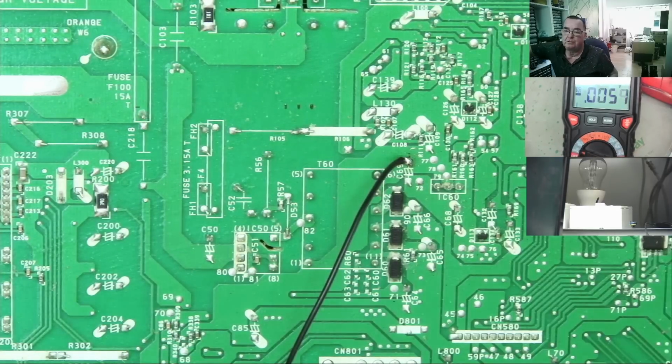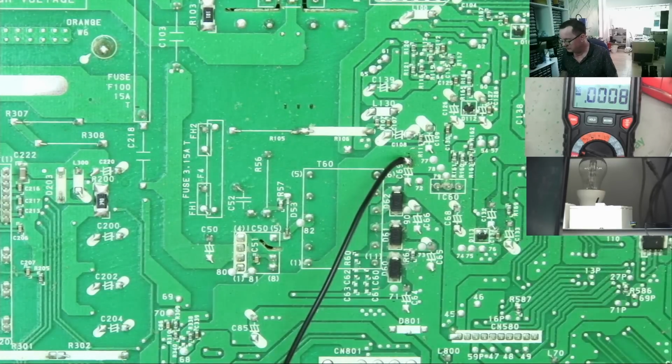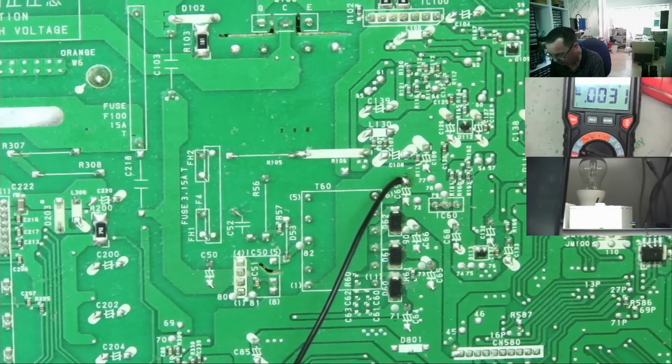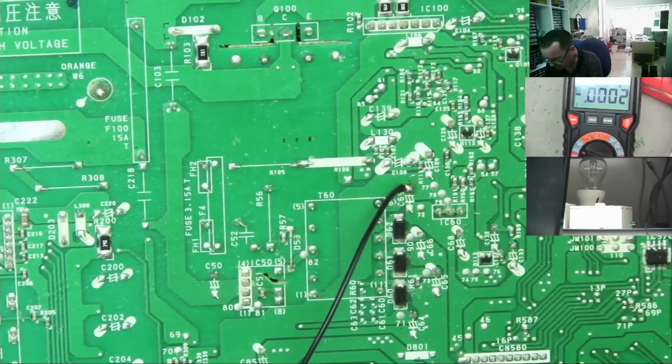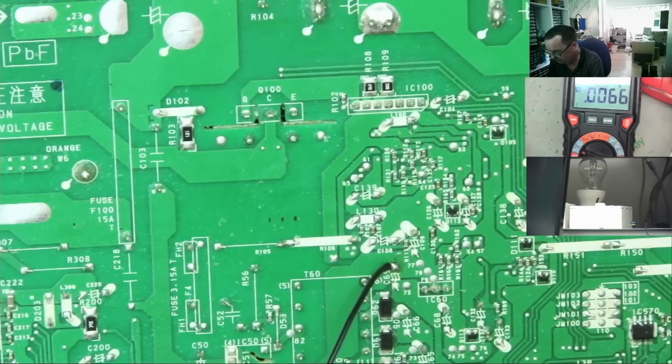Okay, volts range, you can see the current limiting bulb up there, so we're going to switch this on now, and hopefully the bulb won't do anything. It came on bright, so I'm going to switch it straight back off again. That's interesting. That is interesting. Something went tick then. I think something powered up on here, you know. That's drawing quite a bit more power than I would have expected. But no fuses are blowing, I know that much.